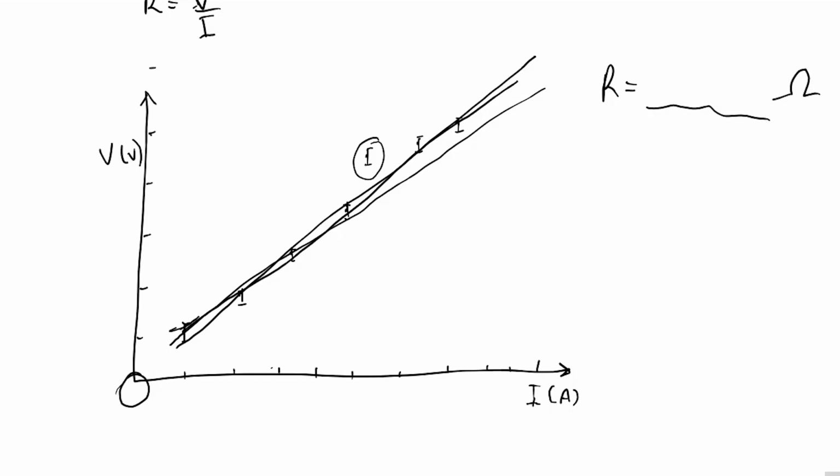So if you use those uncertainty values and work through the process, I think you'll find that you're drawing your graph, draw it really big, draw it with a very fine pencil and draw it very carefully, and you should be able to actually calculate a minimum, maximum, and kind of the best fit value for the value of R. And work out the precision of your experiment as well as what the resistance of this particular ohmic resistor that we were measuring is.